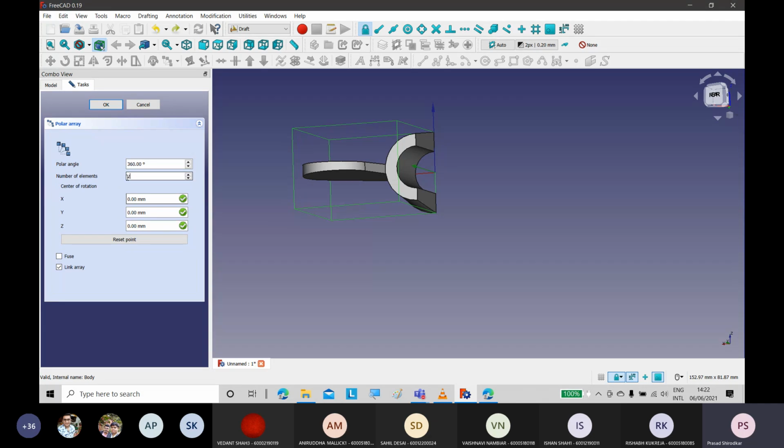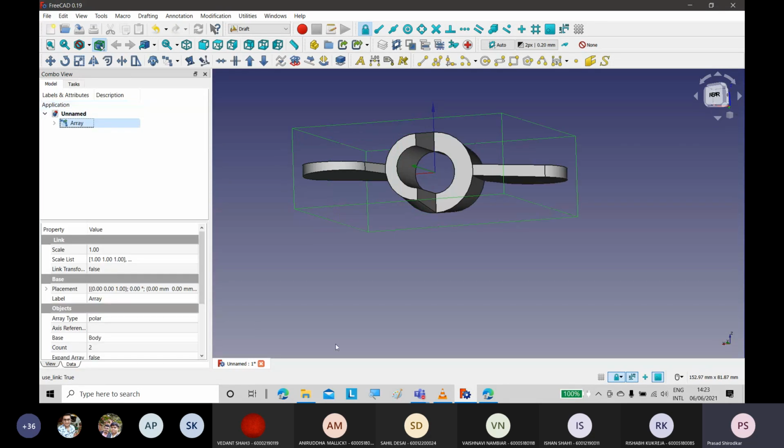So make this 2 and make sure that you hit this reset, and all these values are 0. If you move around the mouse, then the values change, so make sure it is 0. Okay, and if you want to switch off this grid plane, click on tab, come on the screen to reset and OK.